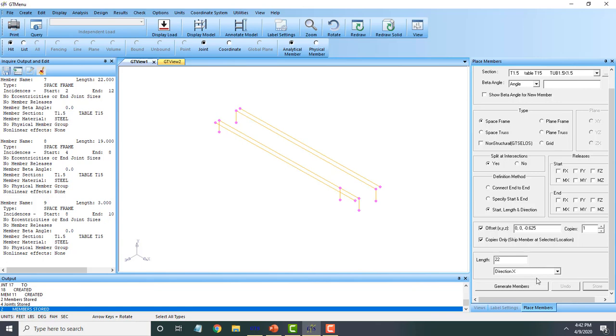Now I want to create the top chord of this bridge structure that we're going to create, and that is going to be at 2 feet and 10 inches. Okay, so note how I'm typing in the dimensions in a mixed unit system, right? And if I click on 0, click in any of these dialog boxes, it'll automatically convert that to decimals for you.